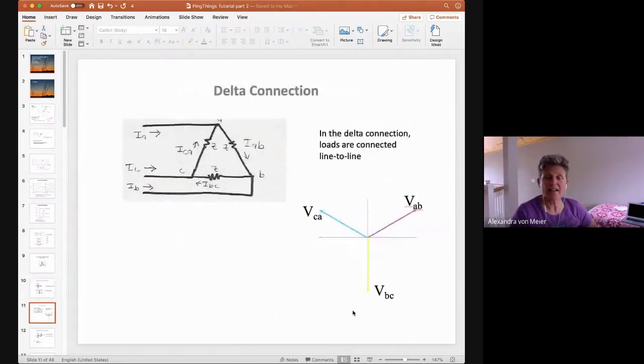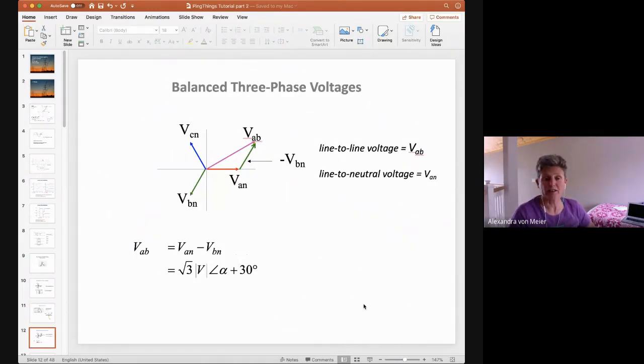So in a delta connection, where we are connecting between two phases, the voltages represent the difference between pairs of phases. And there's still three balanced voltages, 120 degrees apart. But if you do your vector addition or subtraction, which is sort of convenient that we've converted these time-varying quantities into something that you can analyze graphically by its length and direction on a piece of paper, we can do this vector addition here.